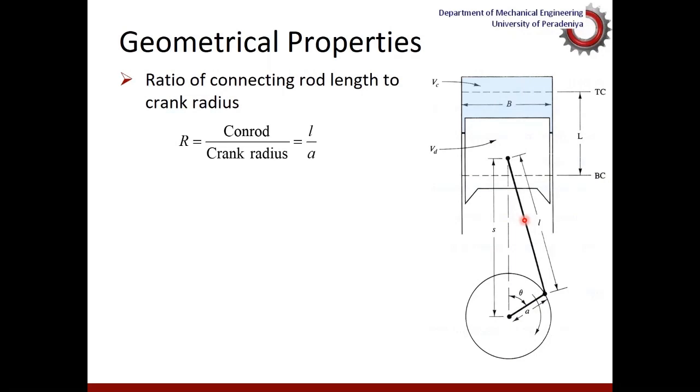So now when it comes to heat losses, the objective function that we look at, when it comes to design, is surface area to volume ratio. You want to minimize the surface area to volume ratio. You want to have a larger volume with small area. That would be the ideal.